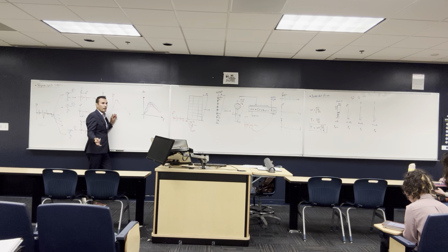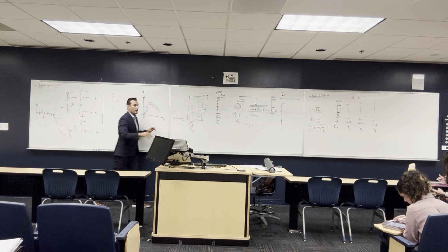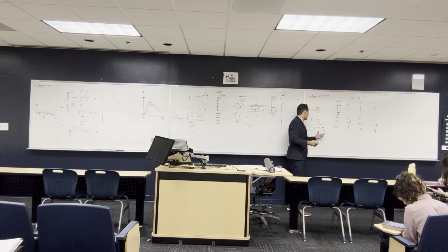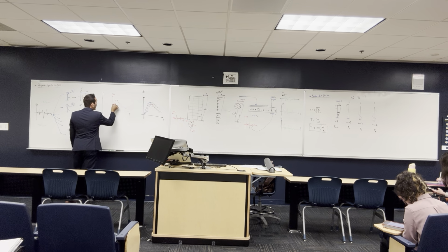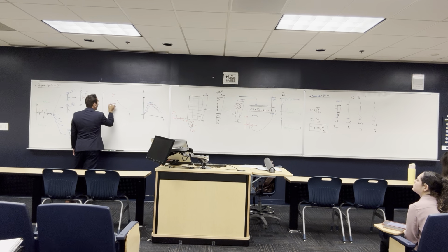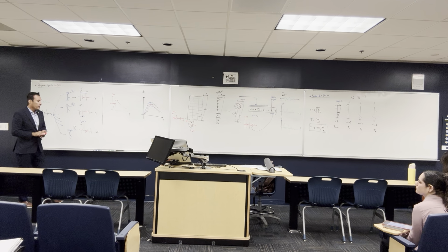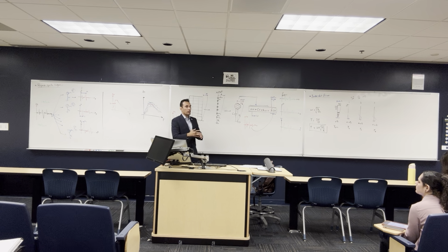Basically right now, for any building, if you know the fundamental period, if you know T of the building, it's very easy. Software can calculate it very easily. You just draw the geometry of the building, and it's going to give you what T is. If you know it, you can just go in the code to this curve, like this, and find what the spectral acceleration is going to be, given the zone. The code has all the information about the earthquake zone of the area that you're working with.